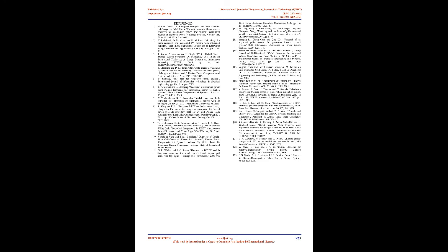Power generated from multi-array PV system with efficient MPP tracking. In Fig 11 it is shown that the converter 3-phase output voltages are under uniform full insolation throughout the system. The powers processed by the cascaded cells are equal in this operating condition. The multi-array converter produces a smooth near-sinusoid output voltage, which makes it a low distortion system. When the inverter cells are cascaded, the physical locations of those cells could be far from each other, and the output voltage vectors of individual inverter modules are in phase and equal in magnitude.